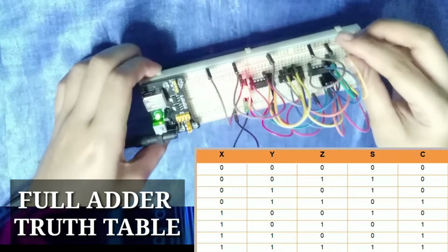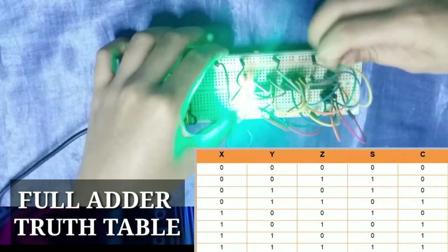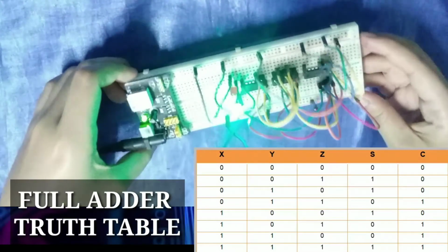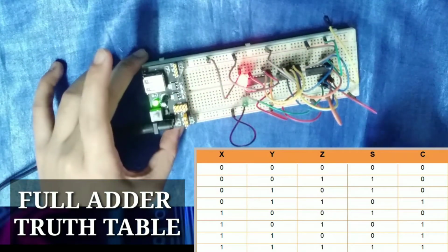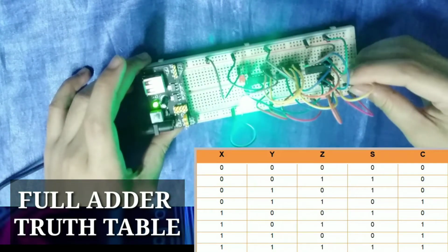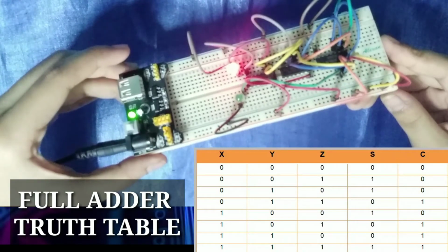Now, if only the input X, the yellow wire, is connected to the VCC and both the green or Y and Z inputs are connected to our ground, as you can see, only the S output, or the green LED, turned on. Now, if only the input Y, the green wire, is connected to the ground or at logic 0, and both inputs X and Z are connected to the voltage supply, as you can see, only the C output turned on, or only the red LED turned on.